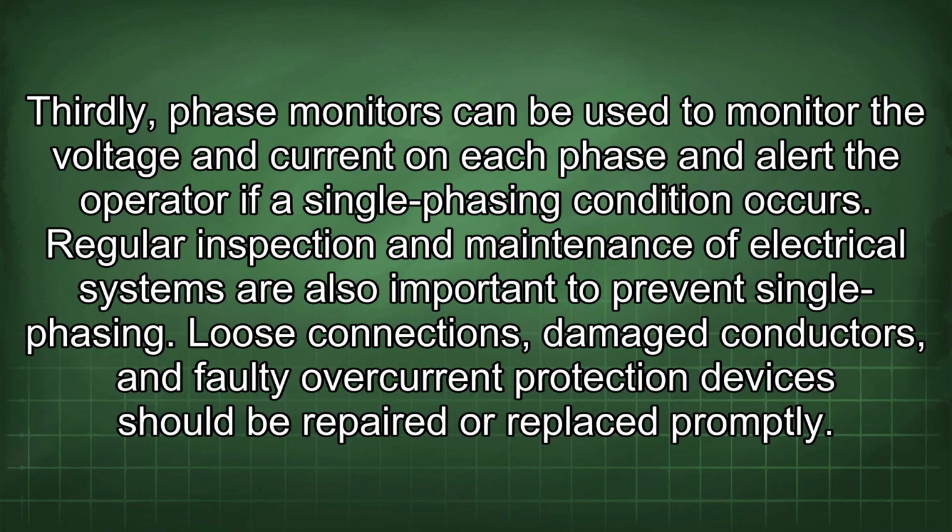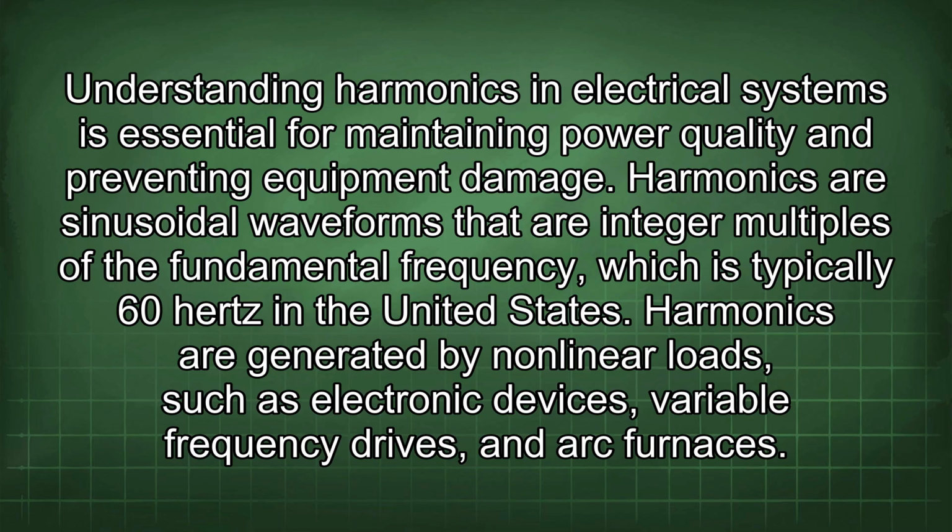Regular inspection and maintenance of electrical systems are also important to prevent single phasing. Loose connections, damaged conductors, and faulty overcurrent protection devices should be repaired or replaced promptly. Understanding harmonics in electrical systems is essential for maintaining power quality and preventing equipment damage.